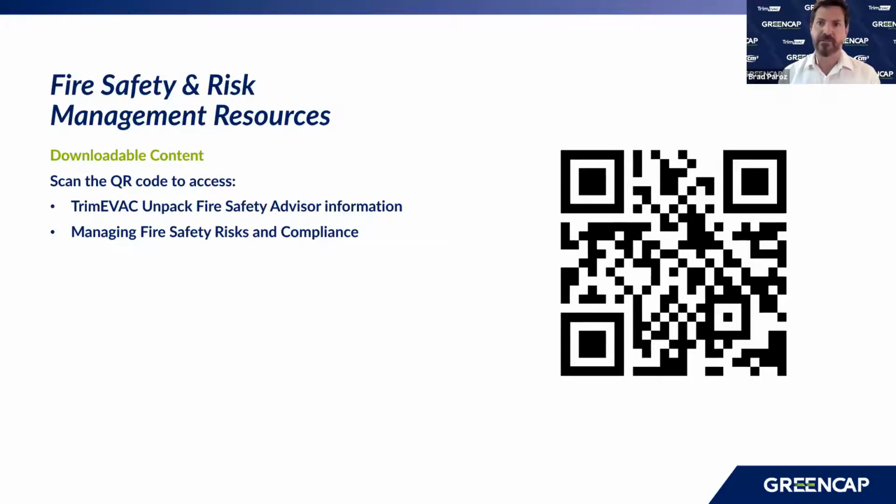But it's not a door, for example, if you're in a retail tenancy and your retail tenancy opens into an enclosed mall, that door is not an exit door, it's a door in the path of travel to an exit. The exit doors are actually then the auto doors off the mall, or the fire stairs off the mall as well. So an exit door, yes, must swing in the direction of egress, but a door in a path of travel does not need to swing in the direction of egress. So that's the key difference.